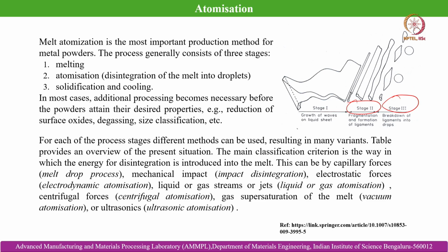Of course, we can develop some irregular size powder particles even by the machining route, that means we can get them from the machine chips of the material, but they are of highly irregular shape, and also we cannot achieve the finer powder particle size that is needed for critical micro components. Generally the thumb rule is the powder particle size should be at least 1/10 of the minimum dimension present in the component.